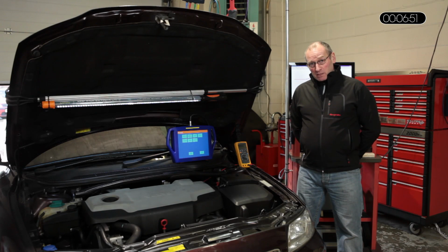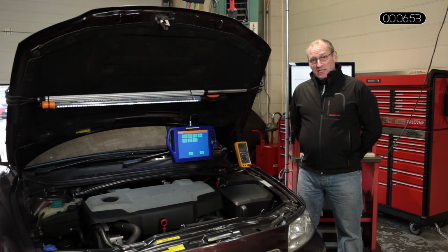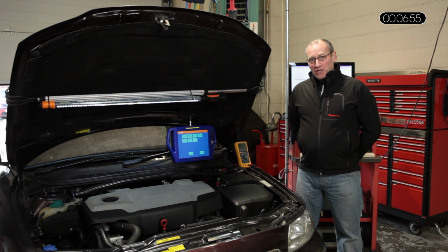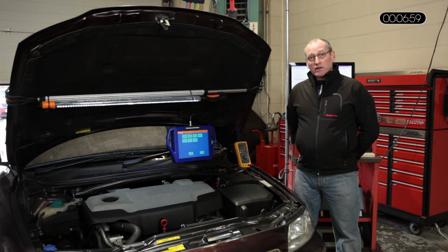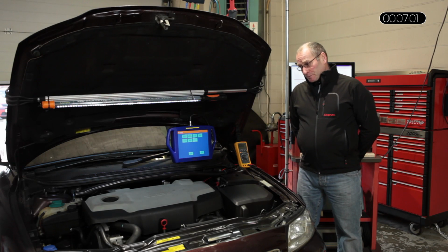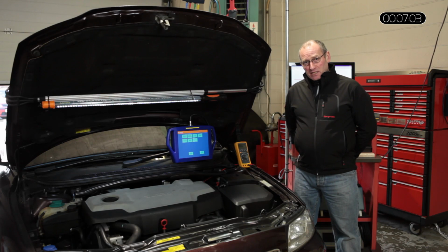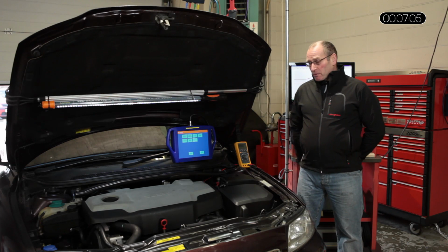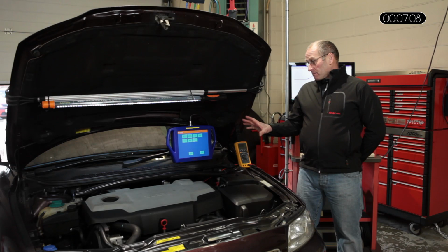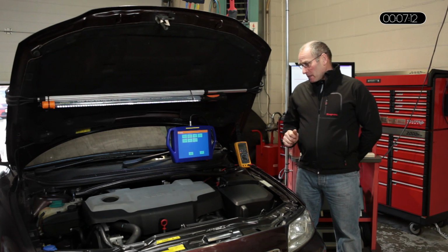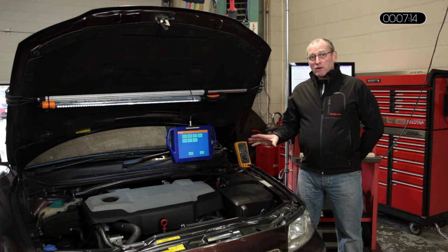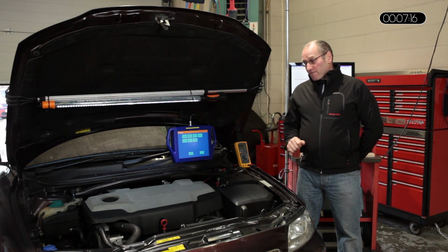After we'd steamed the DPF out, refit it, we then did another manual regeneration process before going for a road test, before re-evaluating the data. I'm going to go through the data shortly with you, but first of all, let me start the vehicle. You've shared the experience of how we rectified the problem, and I can assure you this vehicle now is exceptional. It really is running very, very well.